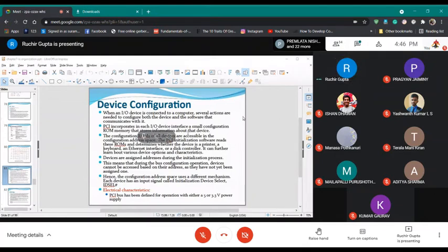Whereas the lower address lines are used to specify the operation and content of the device configuration ROM. Once this happens, out of these 21 locations the host can identify the device, and then the device may request an address in IO space or in memory space, whatever kind of configuration it is.